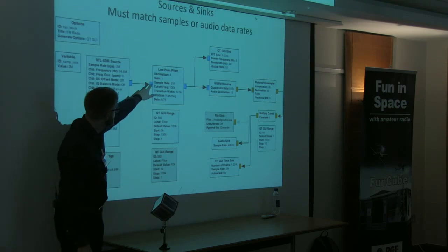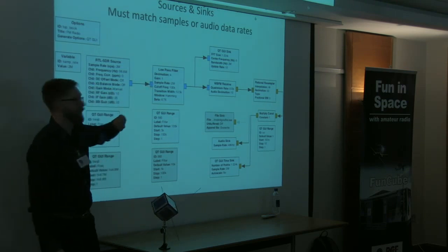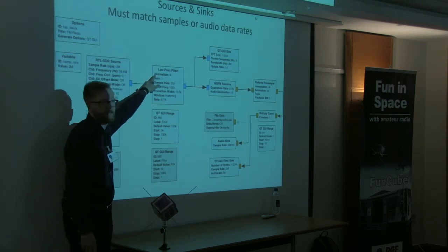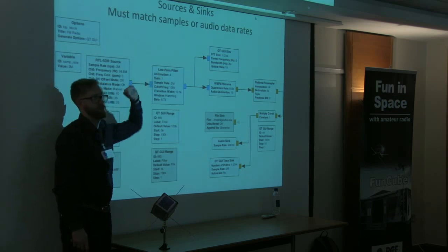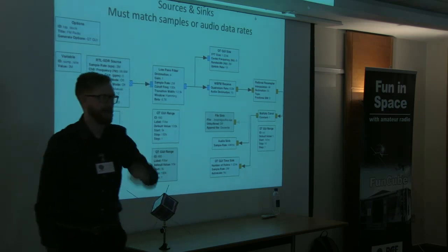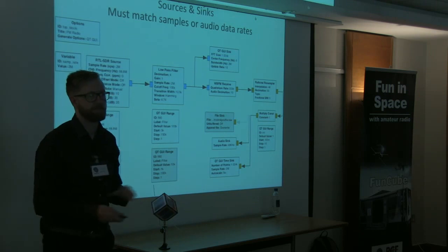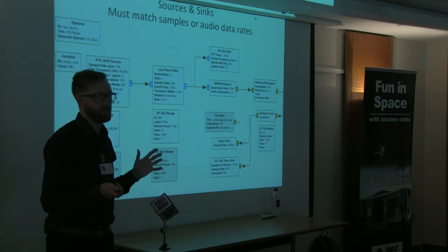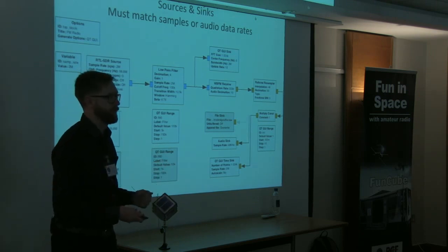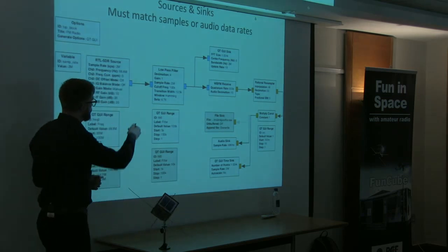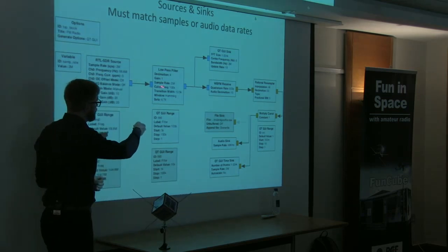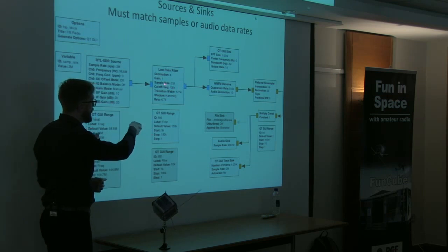So I can pass it through a low-pass filter, and I can then already, at these points, start to decimate my data. And decimation is essentially, in this particular case, just throwing away samples. Okay? I don't want those samples, is all we're saying to that. And that becomes particularly important because as soon as you want to start decimating down and choosing what frequencies you want to cut off with, you can then pass them through there. And these rates have to match.